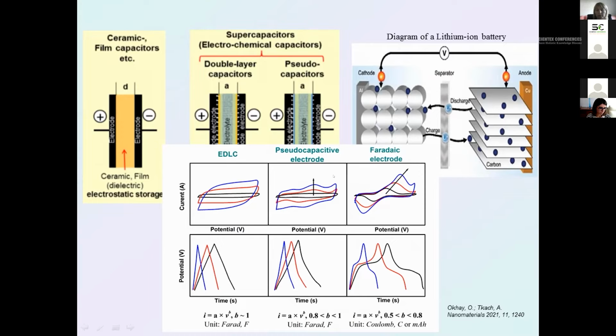So it is very important to understand when we have materials that belong to supercapacitors and materials that show battery type energy storage. The second parameter that is important for this characterization is the charge-discharge curve. For a supercapacitor, it should be a triangular curve, but in the case of a battery, it's completely different.